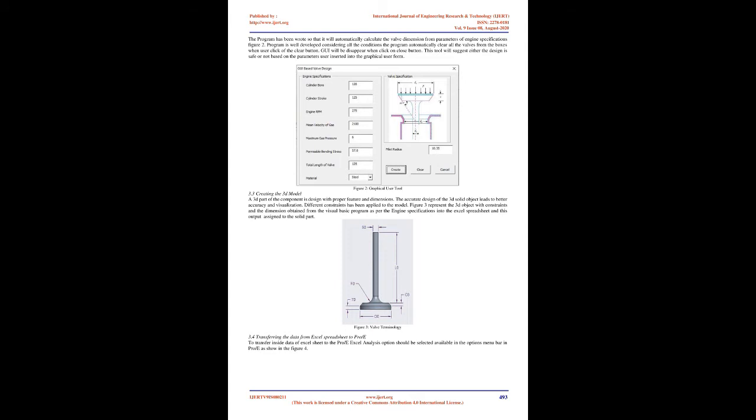The data can be related to the part feature data. Hence the spreadsheet's data is equal to the data of the part, that is, the dimensions of the model. By just changing and updating the data of the spreadsheet, we will update the dimensions of the part.